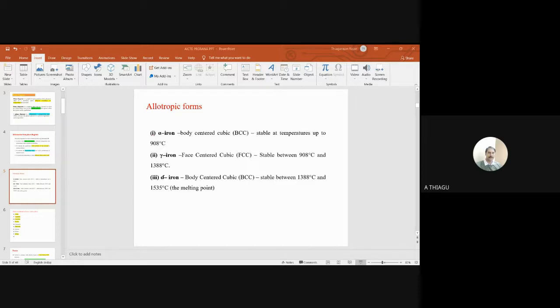Okay, so this is the particular location where we have to find the transformation from liquid to produce two solids. This is the area where we find the eutectic reaction at around 1147 degrees centigrade. So liquid is going to produce two solids. You can look at the reaction for liquid, and slow cooling is going to convert it to solid 1 and solid 2.